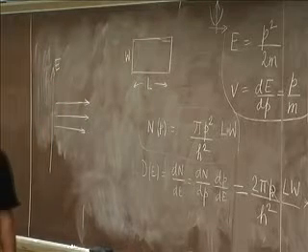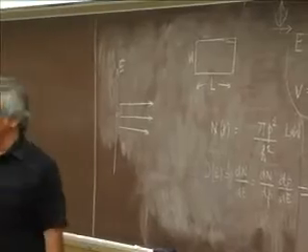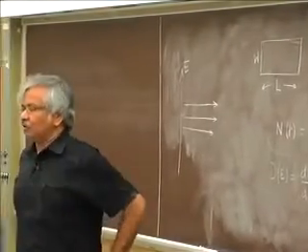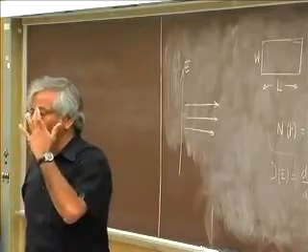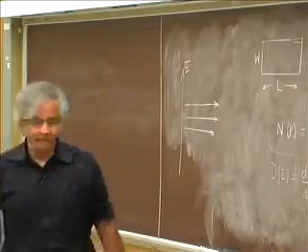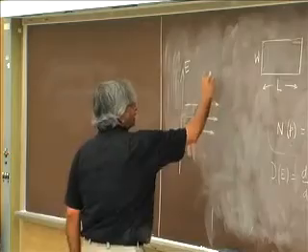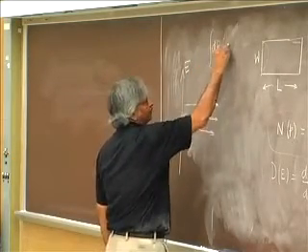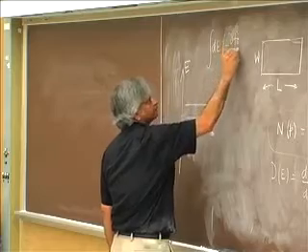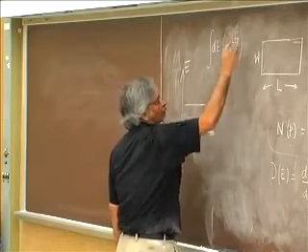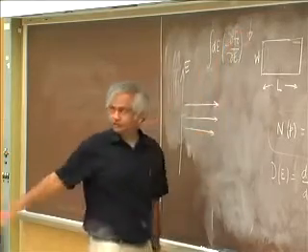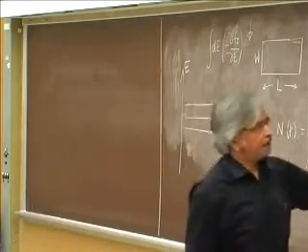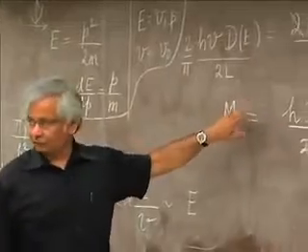And so when I think of conductance, number of modes, density of states, anything I write, it is at some energy. Now you say, okay, but then for this conductor, how do I know what exactly to expect? Well, if it is low bias, it will basically involve integral dE minus del f0 del E of whatever quantity we are talking about. So when I calculate number of modes, it is a function of energy.